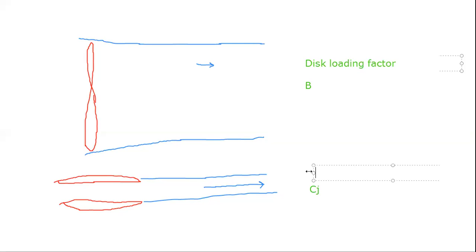In Russian, we use the Greek letter mu as subscript, C mu. But they're exactly the same coefficients. So to properly simulate propulsion in the tunnel, you have to take these coefficients the same for the real aircraft and for the model.